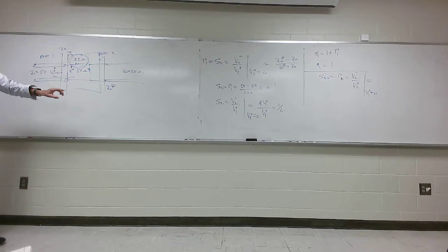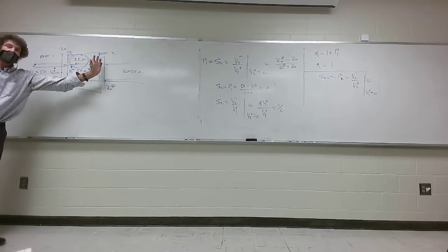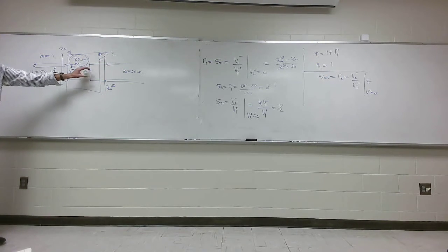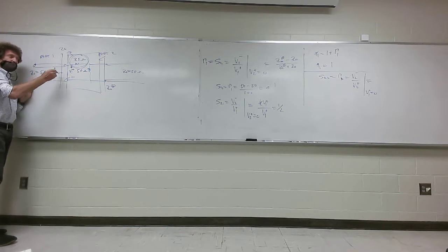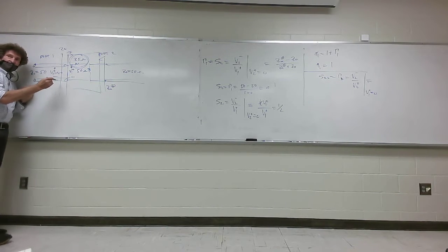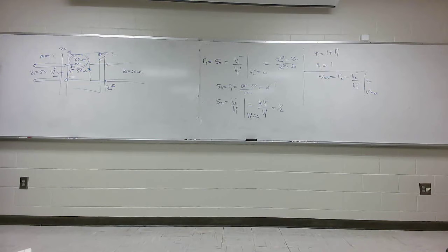Now look. You see there's 50. You're jumping off that transmission line. You're right. You see you got 50 in parallel with something right off the bat. Y'all see this? What's it in parallel with? Well, 25 that's in series with 50. So looking from port 2, this first port is 50 ohms to ground, but it's got that 25 here, and then from here down to ground, I have another 50, right?